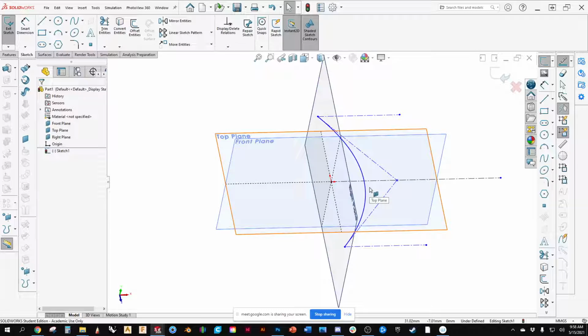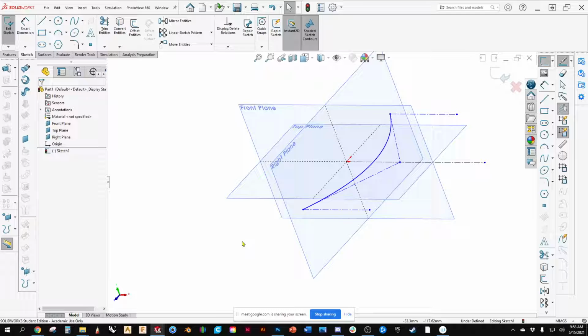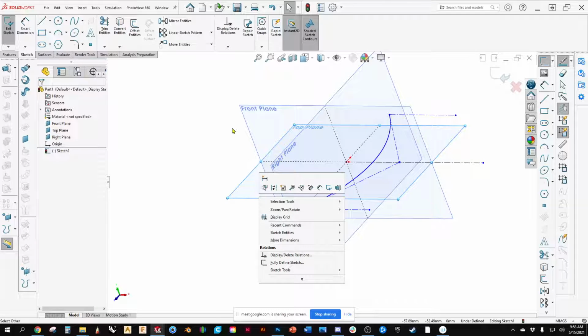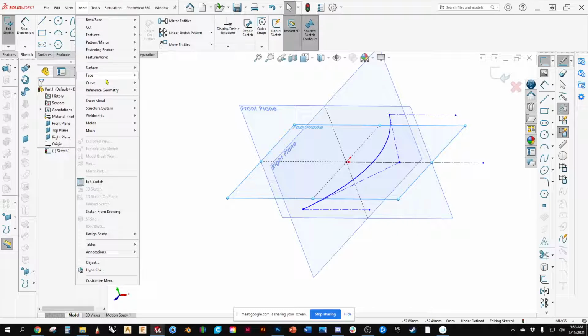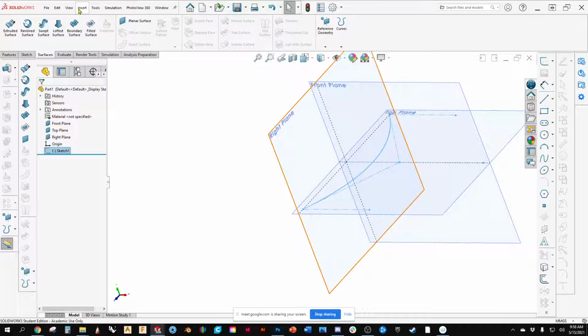Sometimes this is what I'll start by building off of, because again, we talk about a little bit of work up front meaning it may be easier to do downstream. This is going to be where my top surface is. We're going to insert new reference geometry. Oops, got to get out of my sketch first.